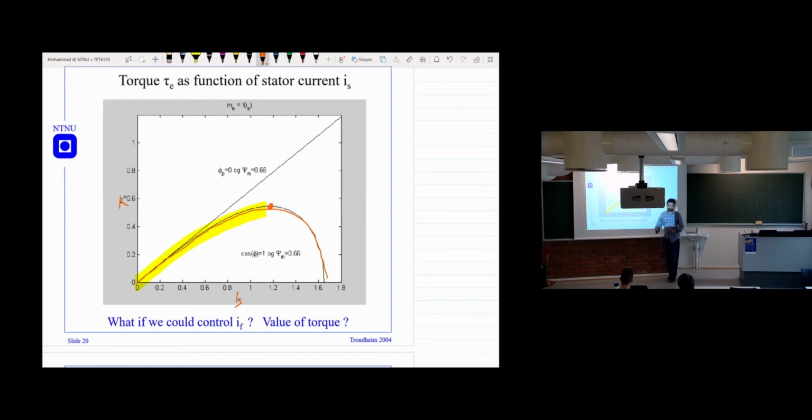And this is not an optimum control for the PMSM machine. But this control was used earlier because we wanted unity power factor, to reduce the current flowing through the converter, because the converter is very expensive. But nowadays, the converter is not as expensive as before, so we want to have an alternate control.